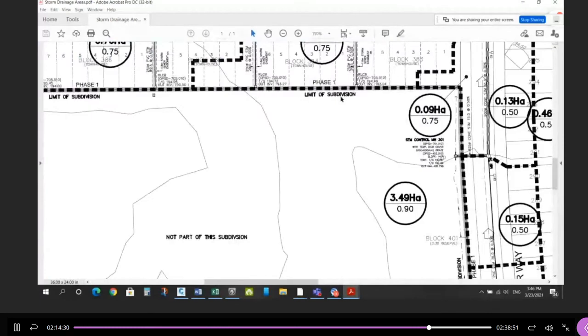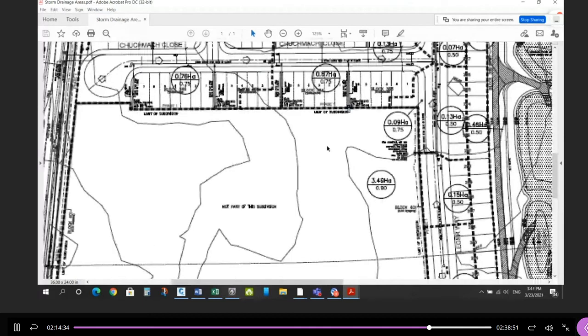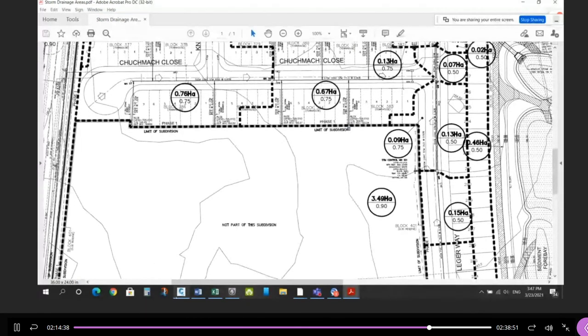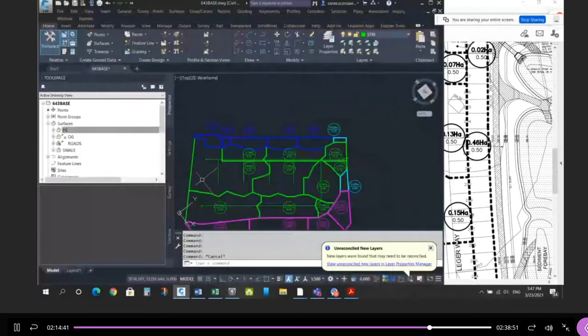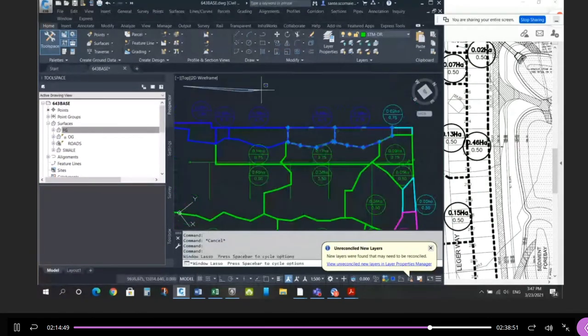We'd have a catch basin here, another one here, another one here. It would look kind of silly, right? So I'm going to take more area this way and find out what happens. How much more area? Well, let's look at the drawing, right? This pipe and the pipes are going to go into the bottom end, the last pipe, and these three areas are going to go into the first pipe.